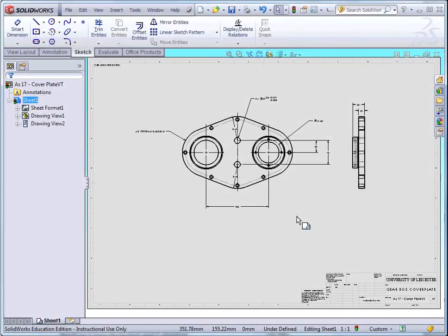In this tutorial, we're going to look at the use of some of the SOLIDWORKS drawing commands. We are going to use the hole callout tool and the section view command. We're also going to look at producing hole tables, detailed views, cropped and broken out section views. We will finish off by looking at exploded drawing views, balloon referencing and part lists.